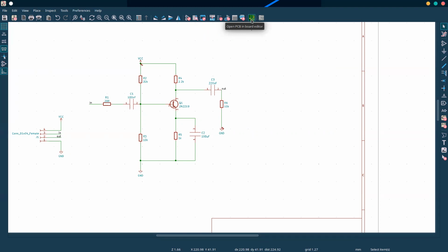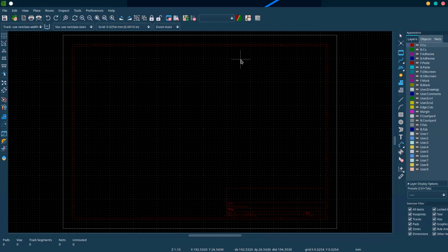Anyways, I don't want to drag this out too long, so we're gonna speed run this next part here. We have completed a schematic, so now we can actually lay out the PCB. So click the PCB board editor button. That's the green one there. Actually, don't go back and do that. Yeah, do it from the schematic, or else the two applications won't be linked. File, tools, there you go, which is the editor.